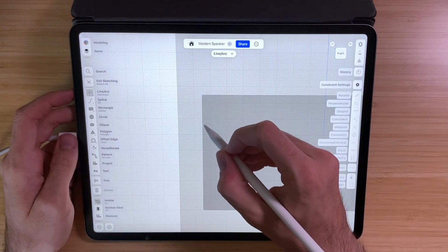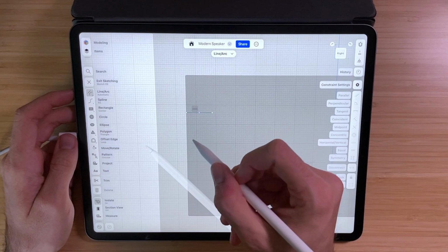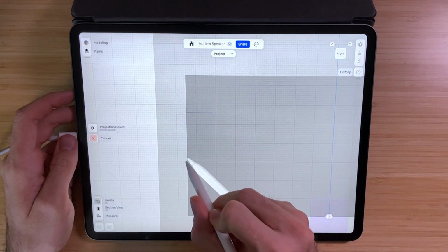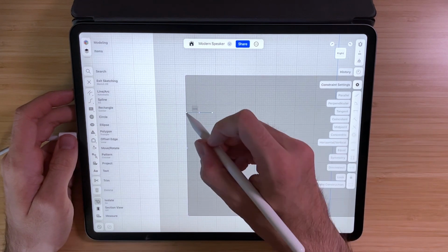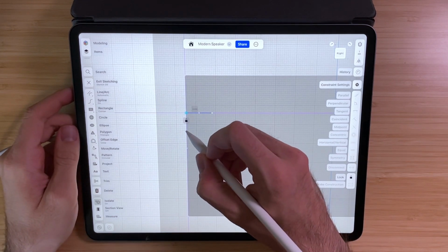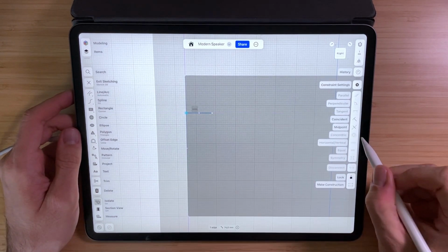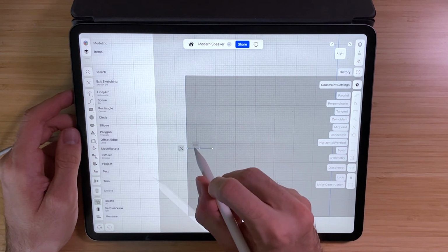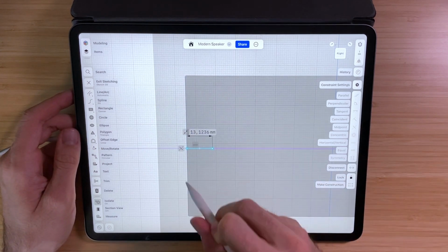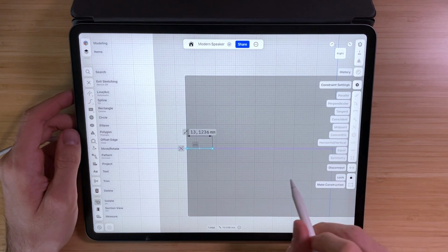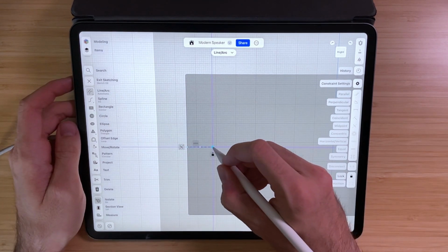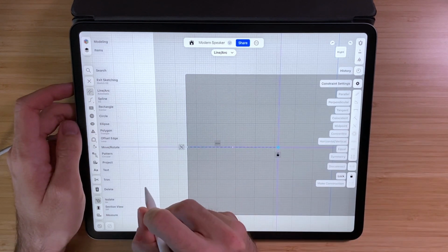So let's start with a line on our sketch. And I need also my edge here. So let's project this edge, hit done, and then click the starting point of our line and our edge, and then select midpoint constraint. So now this line is in the center of our projected curve. Next, we'll make it a construction, and we'll just select this endpoint and make our line a little bit longer.